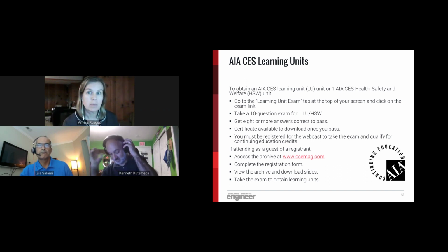So that's an excellent question. The short answer is there is a lot more arc flash mitigation on the AC system than the DC system. The nature of the fault, the zero crossing on the AC system, just lends itself to a lot more mitigation techniques. On the DC side, I see some of these questions, between solar arrays, fuel cells, batteries, all that type of systems are all on the DC side. So there are more and more DC systems that need to be studied. And programs like SKM, ETAP will do a DC fault analysis for arc flash. So it is very important to do that.